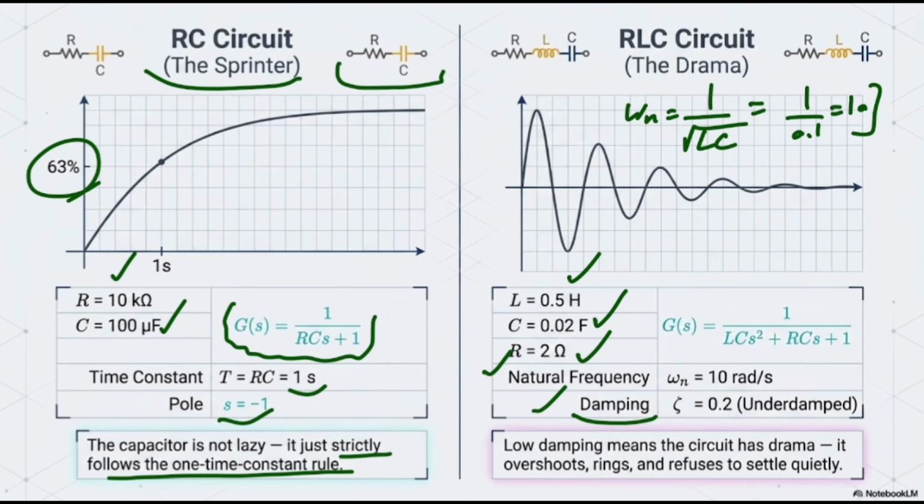Another thing is damping, or zeta. This damping means how much stiffness your system has against the changes related to the input itself. So the output is going to follow the damping, and wherever your damping is bigger, or close to 1, it means your system is strict, and whatever oscillation you have in your input, your output can handle it way better. On the other hand, if your damping is close to 0, it means your system is not configured in a way that it can handle different kinds of oscillation, and it's going to be bouncing and jumping from one point to another.